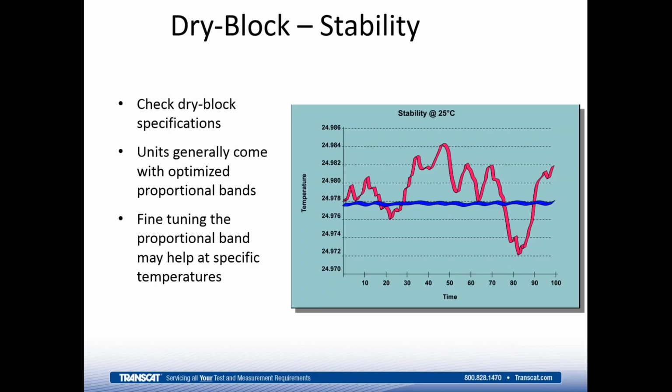Now with a dry block, you can actually get in there and control some of the settings, like the proportional band and things like that, if you think it's not stable enough. Usually things are set correctly though, so that sort of thing would not be necessary.